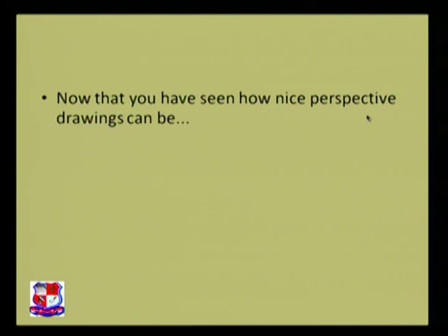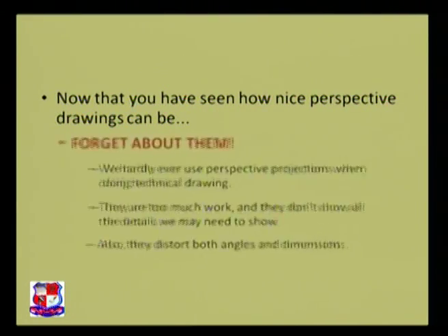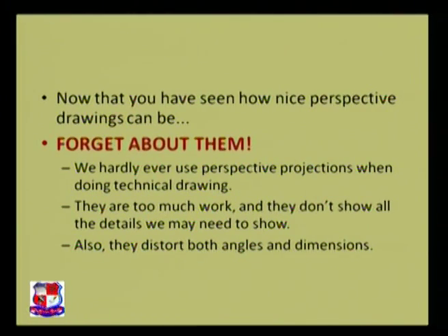Now that you have seen some nice perspective drawings, what do we use them for? We hardly ever use perspective projections when doing any sort of technical drawing. Perspective projections are basically for representational purposes only. If we want to show this kind of drawing to a non-technical person, we can use it. But if we are talking about any sort of technicality, we hardly use this kind of projection.